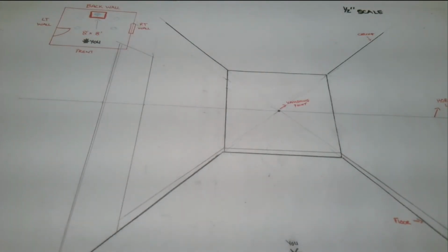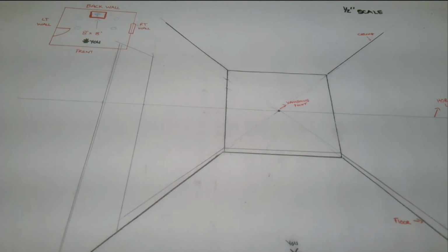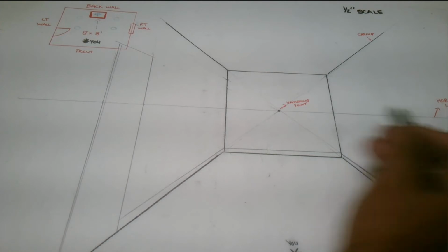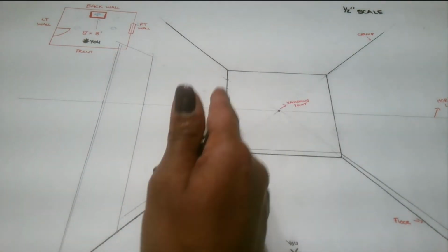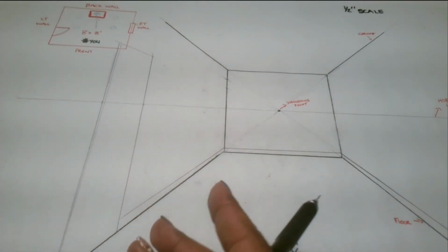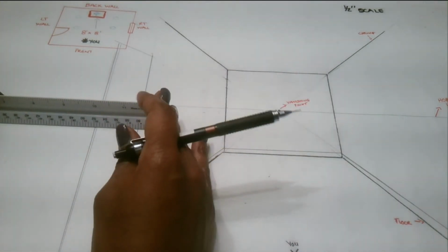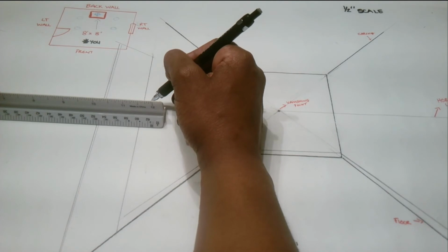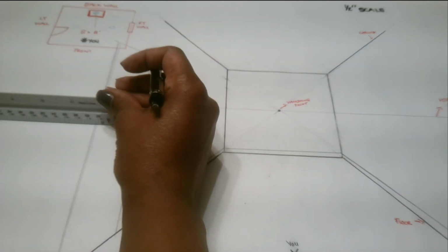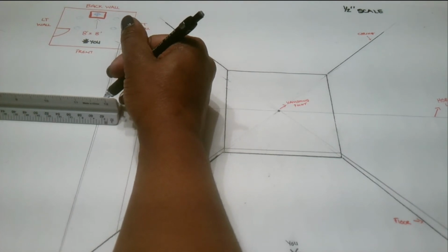Okay. When you want to add things such as door trim, your measurements and the way you take your measurements again would be the same. You're into the left side of your wall. You're going to concentrate on taking your measurements off your horizon line. Using your 1/2 inch scale, you can just simply measure right over from the side of the door. I'm just measuring 2 inches of door trim on both sides.